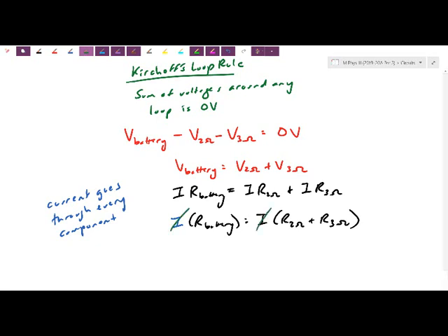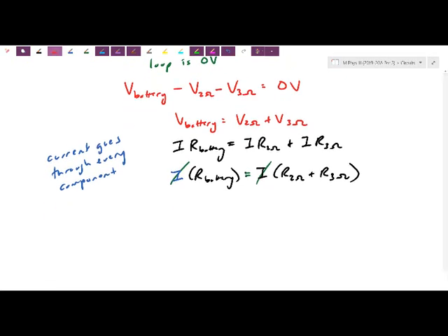This current and that current are going to die away. So what this actually generalizes to is, because the current is identical, to find the equivalent resistance in a series circuit, the equivalent resistance, that's what the battery is applying. It's a little bit easier to think about just as a total. What combination can I replace my battery with? This is actually going to be R1 plus R2 plus any number of resistors that you have.